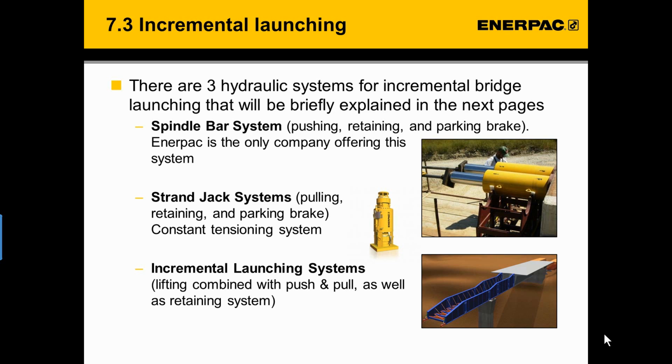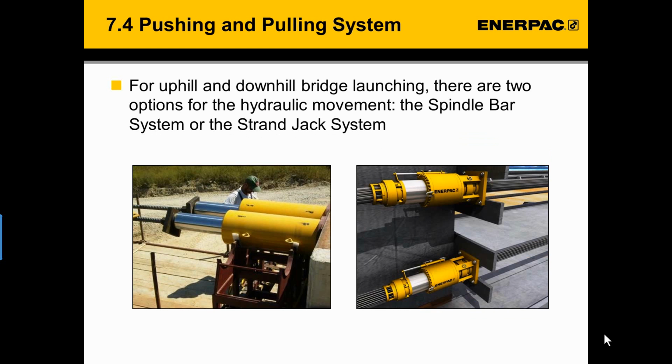The strand jack system as a constant tensioning system for pulling, retaining and as parking brake. And incremental launching systems for lifting combined with push and pull and also as a retaining system. Pushing and pulling can be done with two different systems: the spindle bar system and the strand jack system.